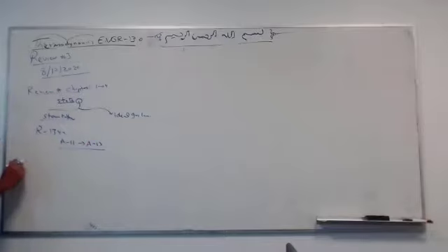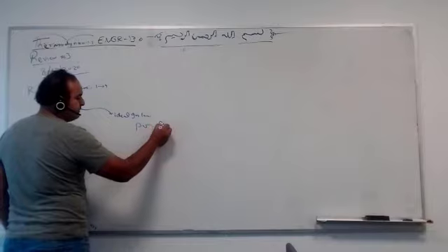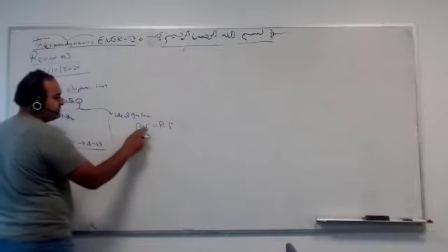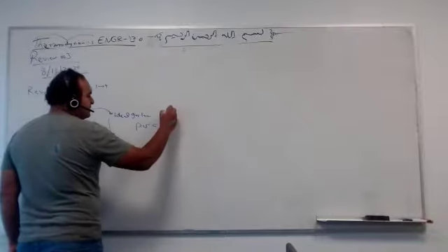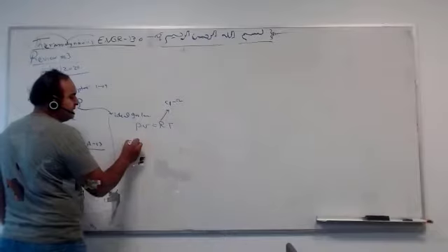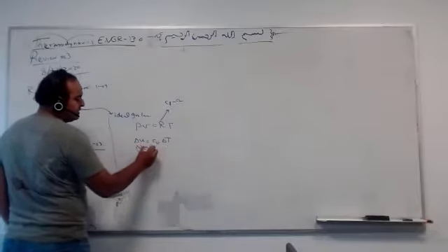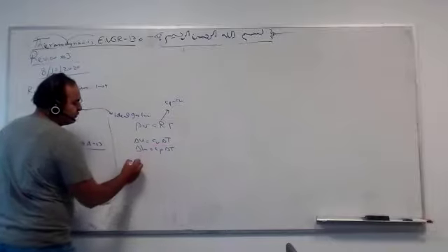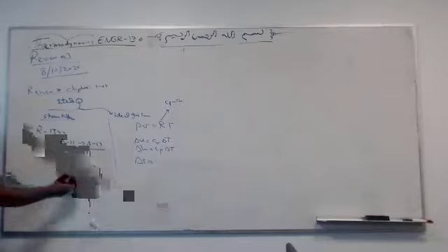Ideal gas law, just PV equals RT. It is a very, very simplified form: pressure, specific volume, gas constant, T. The gas constant from the table or just Cp minus Cv. And we can say delta U equals Cv delta T, delta H equals Cp delta T. The same for delta S. If you want S, here S is easy. It's an extra column in the data.